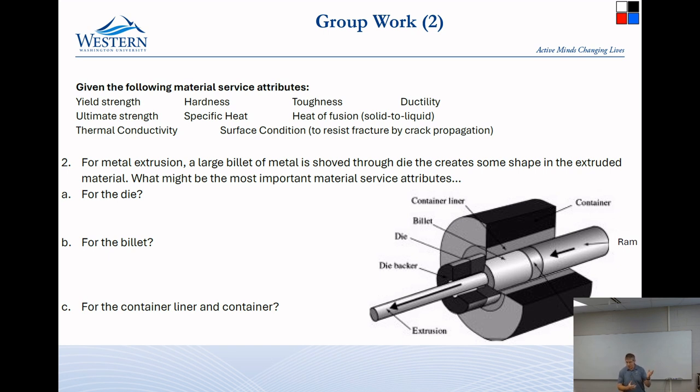They do all kinds of really cool things with it. One of them is you take your aluminum block before you put it in there and you roll it in shattered glass or glass powder. Then when you start compressing it, the temperatures will melt that glass around the outside, and it puts this little layer of liquid that keeps friction from happening between the two. Pretty cool. Like a lubrication. Yeah, it becomes a lubrication, and then at the end you can just break it out of the inside and use it. Wow, that's awesome. Okay, what else is really important for the die?